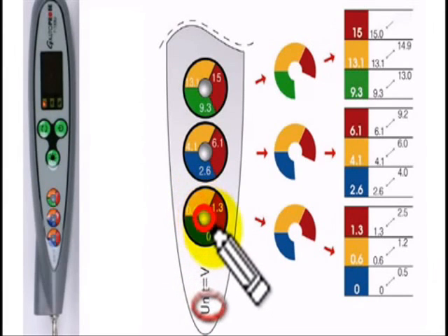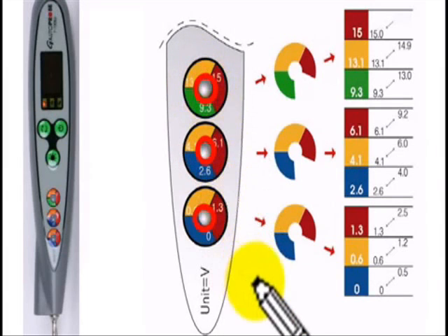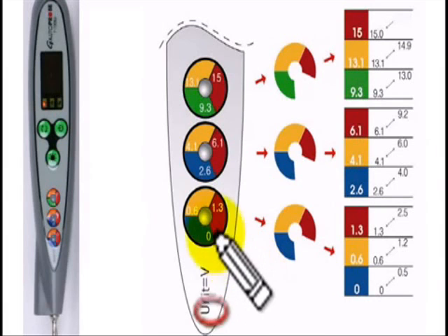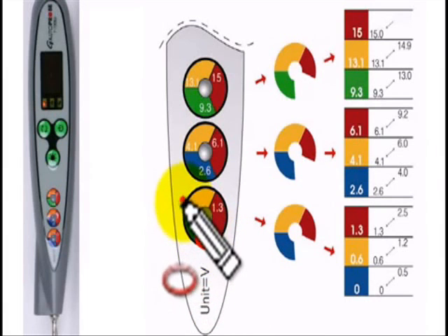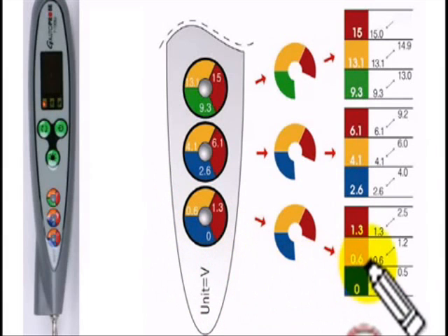Let me explain the color table. These 3 lamps actually are not lamps. They are reflectors letting the light of the lamps out. Each reflector has 3 LED lamps showing the colors marked. The number on the left side of the circle indicates the lowest voltage. Blue lamp lights up between 0 volt and 0.5 volt.